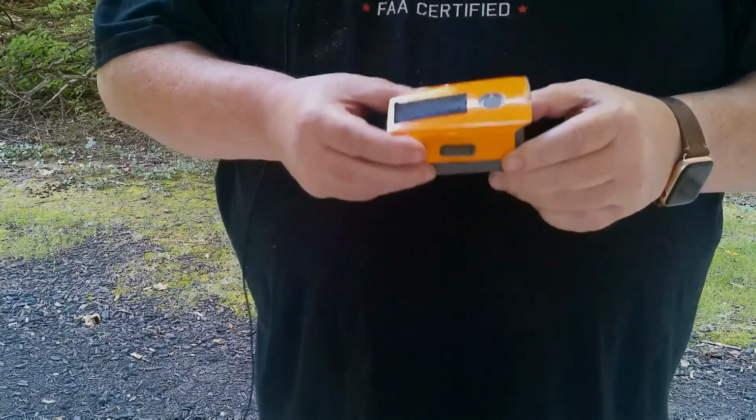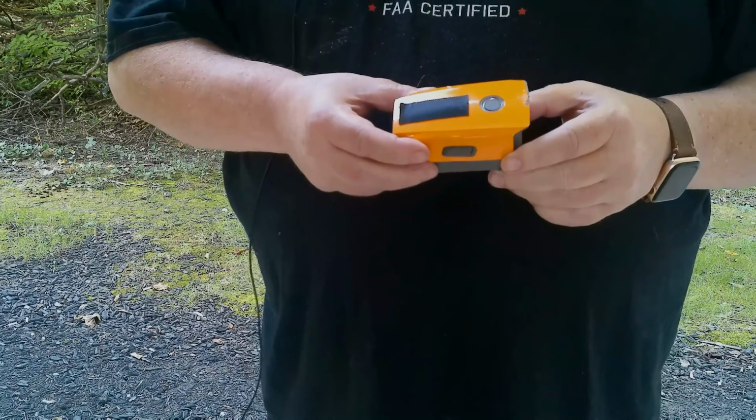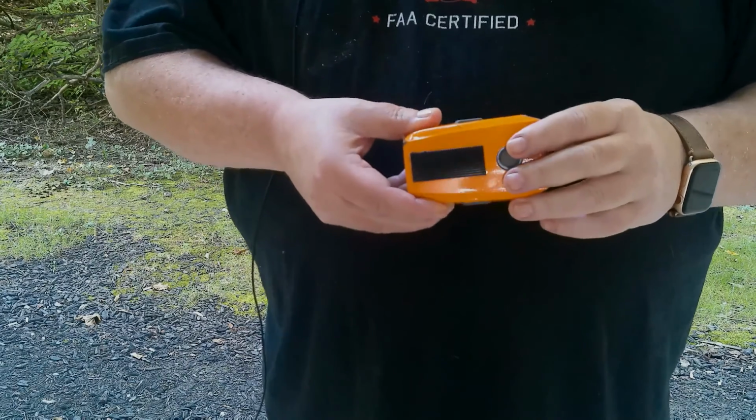Drone batteries are not normal batteries. They're lithium-ion polymer batteries. These batteries have a polymer gel inside, and that gives them the property of being lightweight and holding more capacity during flight. Batteries need to be inspected every time that you use them. The number one enemy against battery life is overheating.